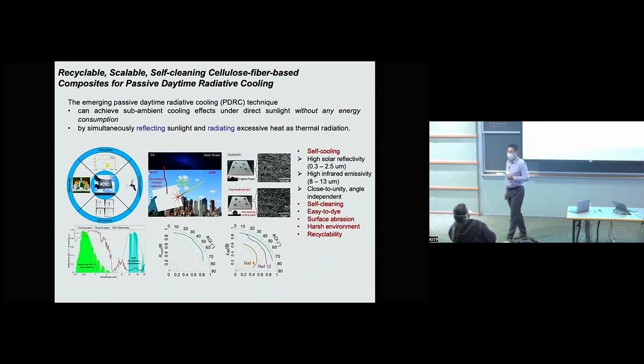We simply rely on the material itself. So how does it work? Let's say you have a thin film material, or you design a material. This material has two goals. Goal number one is to reflect as much energy as it can. Sometimes, as you have already read in some articles these days, Dr. Xiulin Ruan's group at Purdue University invented the whitest paint. The whitest paint can reflect more than 99.9% of the solar energy. This is goal number one: try to reflect most of the sunlight.